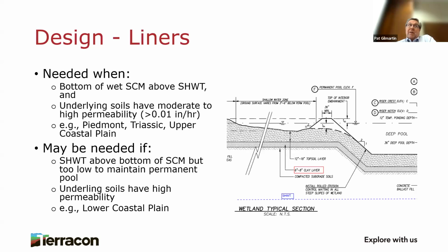The other thing that we get into a lot in the Triassic Basin, Durham, Research Triangle Park, is fractured, partially weathered rock. We'll see a wet pond excavated down 10, 15 feet, and it's nothing but fractured weathered rock, which maybe the contractor can rip or has to blast. And we get asked all the time, will my pond hold water? And you're like, well, if the rock is too fractured and the water is another 20 feet down, maybe it won't. But there are things that we can do.